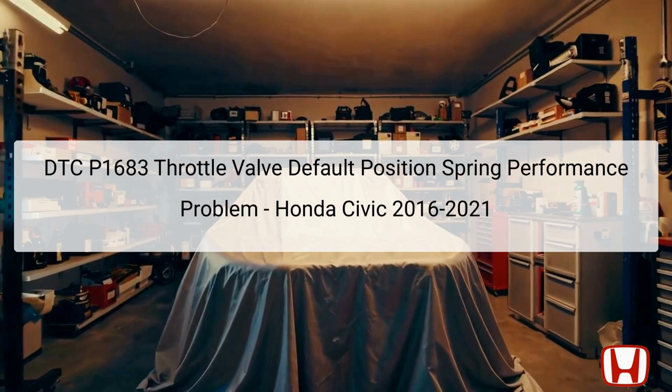Within this system, the throttle body plays a crucial role as it controls the air intake into the engine, influencing engine performance and fuel efficiency. The throttle valve is activated based on input from the accelerator pedal and other sensors, ensuring precise control over the engine's power output. If the throttle valve does not return to its default position correctly, it can result in adverse performance issues. This is why understanding and addressing the P1683 code is critical for maintaining optimal vehicle operation.